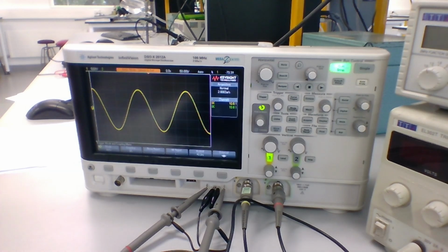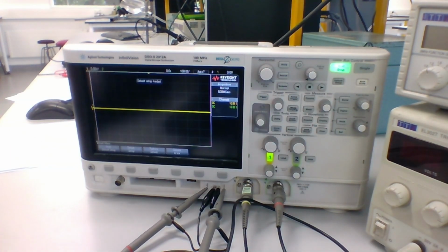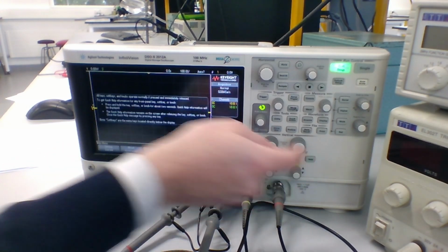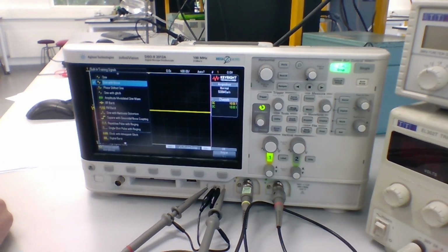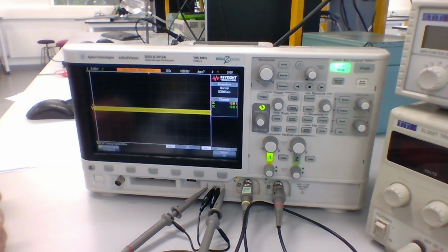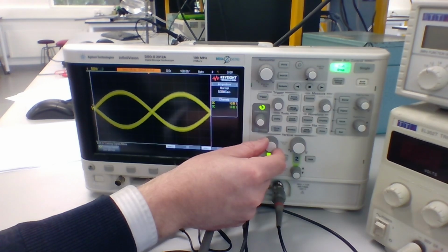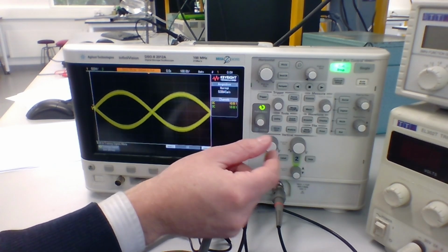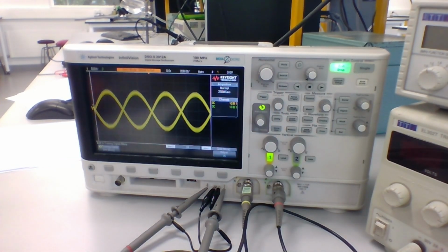Okay. For lab 3, what we're going to do is first of all go back to our default setup. So again, just put everything back to a nice consistent state. Again, we're going to turn our training signal on, but this time rather than sine, we're going to select the one that's called sine with noise. We're going to enable that output. We're then going to scale the oscilloscope. Again, we're setting this to 500 millivolts per division vertically, but we're going to set this to 200 microseconds per division horizontally. We're looking at a different signal here, different frequency, different period. We need a different time base.